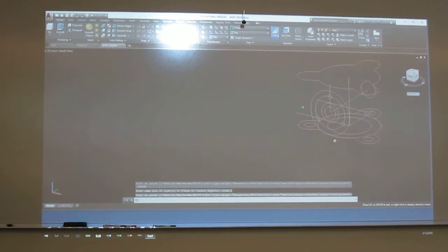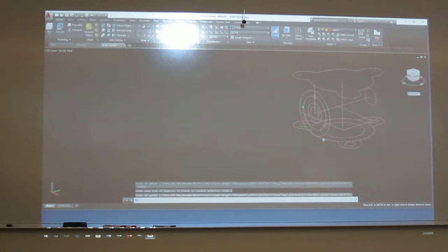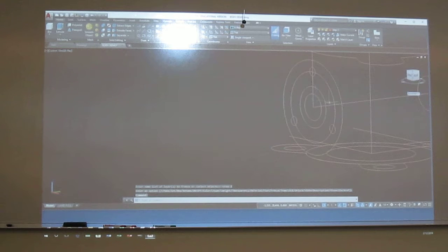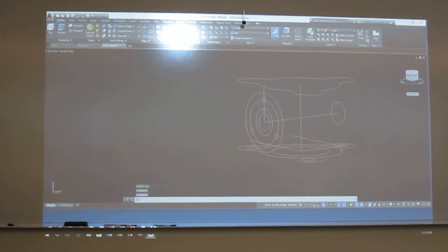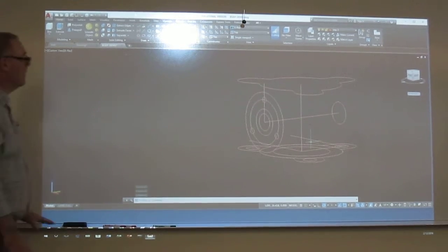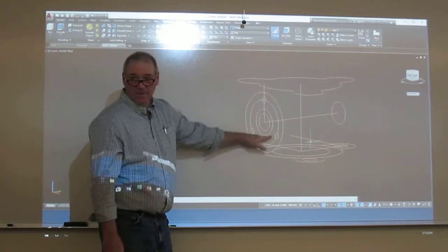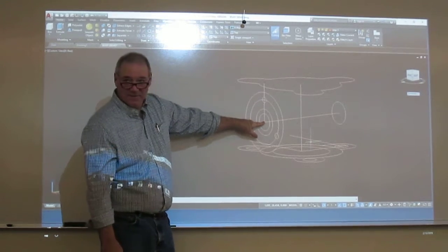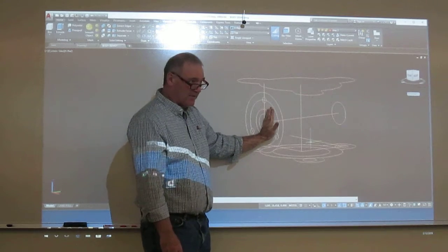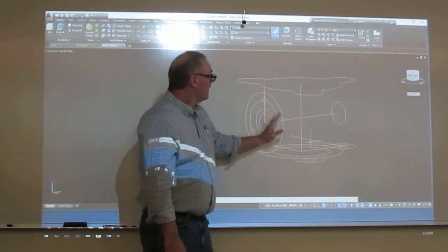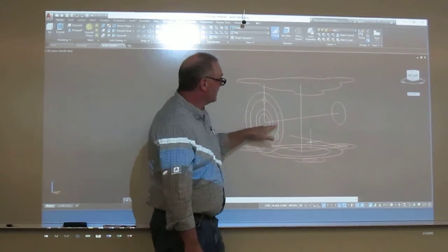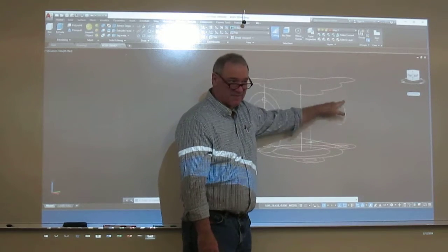Now here I've kind of put it all together. On this one, I went to my front view, and I drew all of these shapes that are right off the front view. Notice they're sitting right here on the front end, because that's where every one of these shapes go. Now this was drawn with the front UCS current. This one was actually drawn here, and then I just moved it with the snaps from there to there. This is that back little piece that sits off the back.